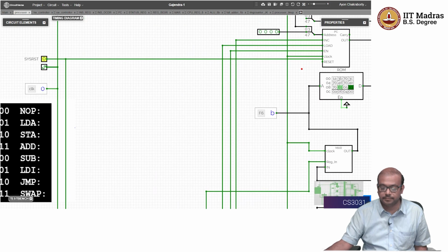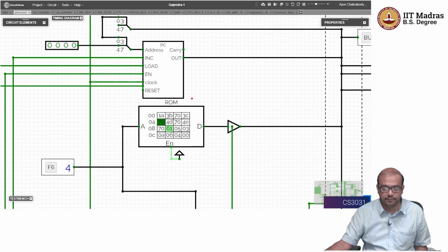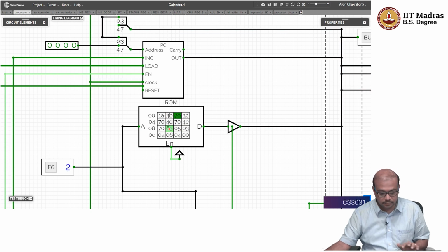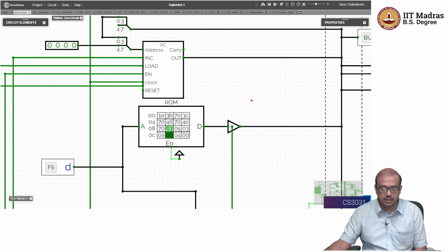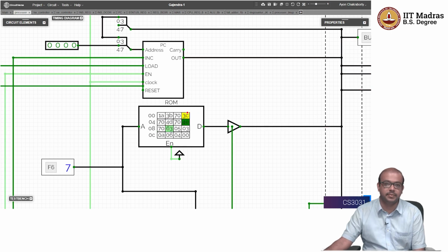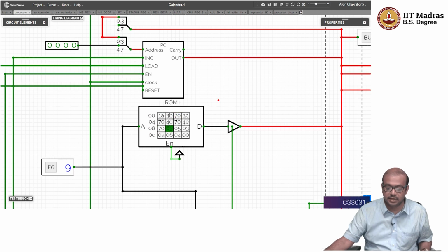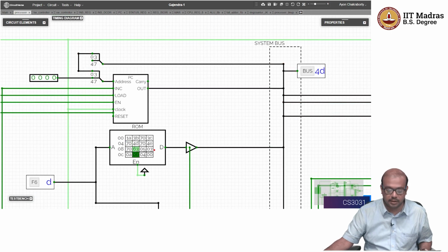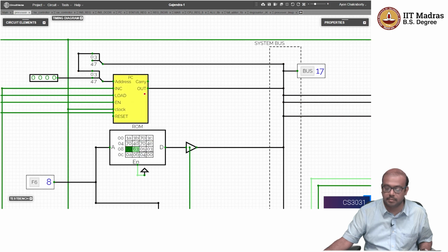So if you follow the jump instruction very carefully, after it reaches 61, it will go to the first location. See, if I want this to jump to the fourth location, let's say 3C, so 0, 1, 2, 3, I want to write here 63. So once it comes to 63 or this location, it will go here. See, it has gone from 63, it has gone here. It's a jump instruction. So what is happening in this case? This value 63, the 3 is going to be loaded to the program counter.